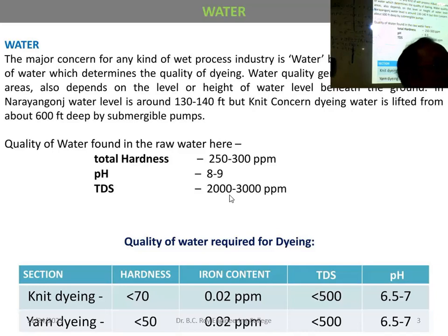Why? Because calcium and magnesium type of ion, which is bivalent, reacts with soap, not sodium and potassium ion. If you have sodium chloride in the water, that will not produce hardness because it will not react with soap. Reacting with soap or not reacting with soap, that we are considering as hardness. That is hardness. Hardness causing ions, calcium and magnesium ion.